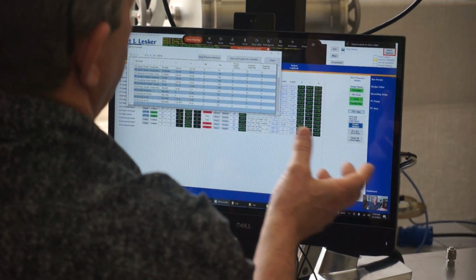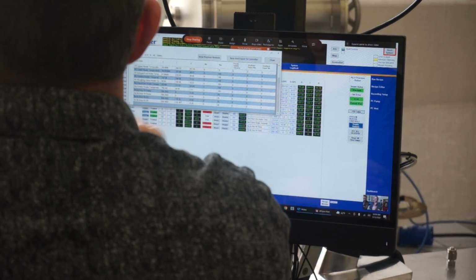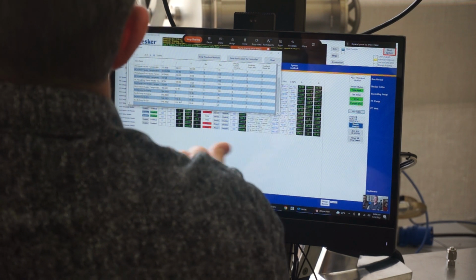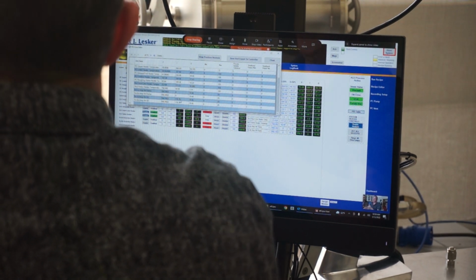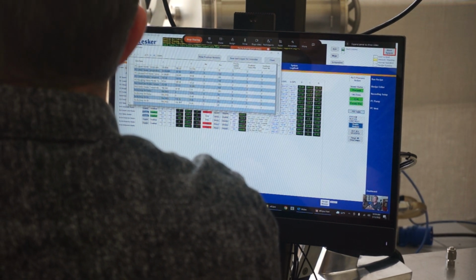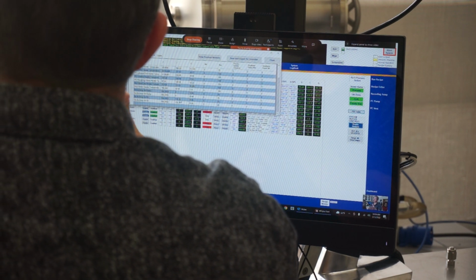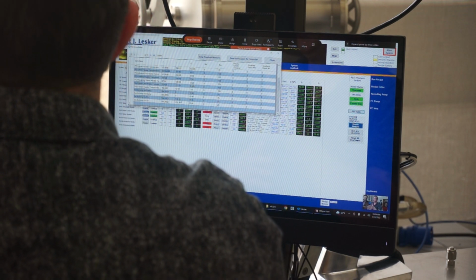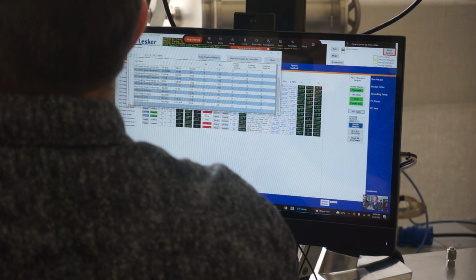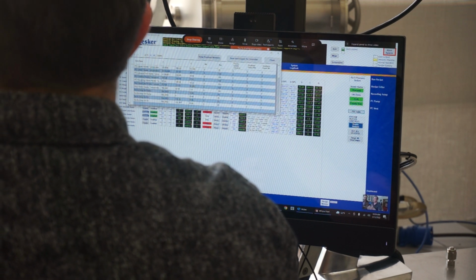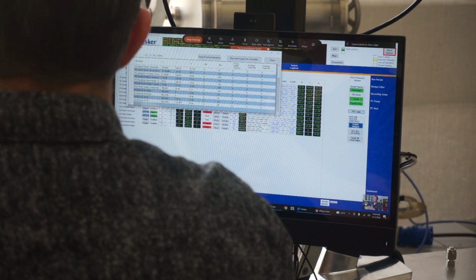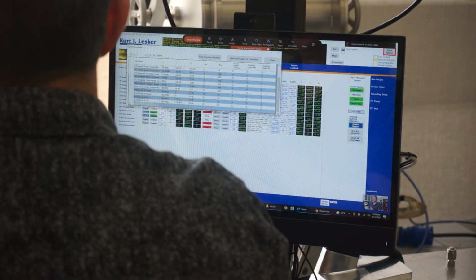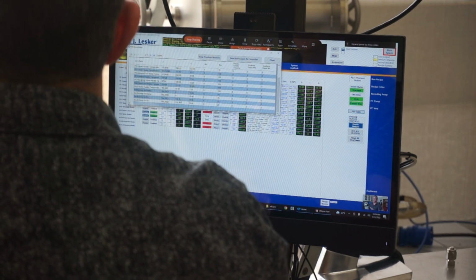Or we could tell you to wrap the heater on an empty ampule, a water ampule, maybe not that exact precursor, and then we'll run the temperature up to whatever we think should happen, and then we can run a tuning program to tune to those PID values, which is a different set of software.